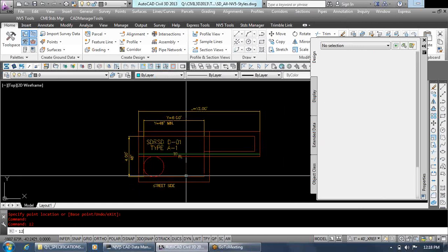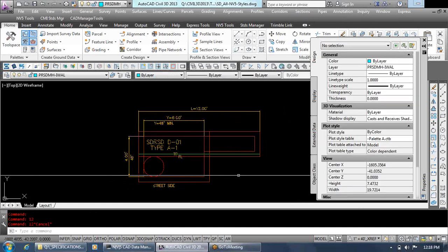Stupid question here. Jason, when you're staking out these, what are you staking? Are you staking four corners, or the insertion point, or are you staking the curb inlet? For staking, we stake the street side, the front two corners, and it's up to the box builders to know what type of box they're building. Is that the inside of the box or outside the box? Outside corner.